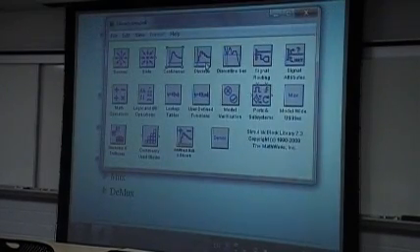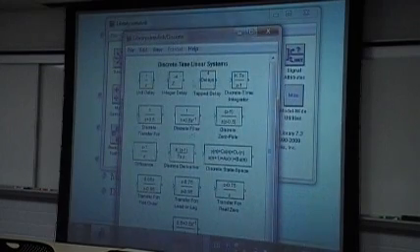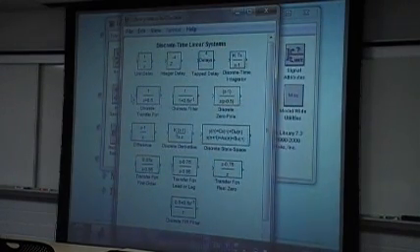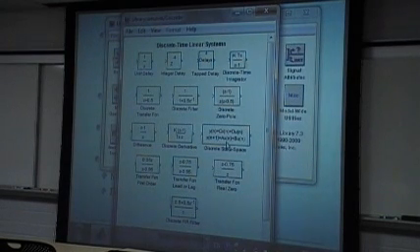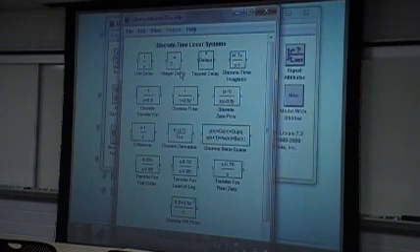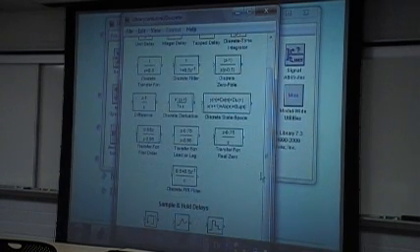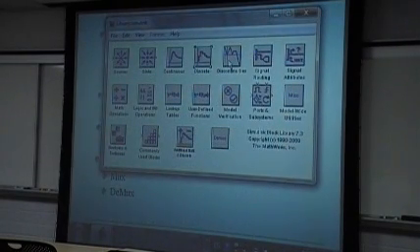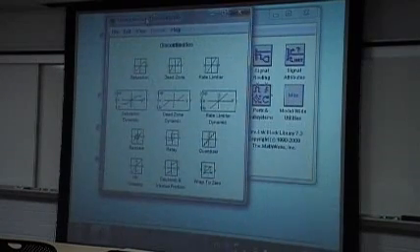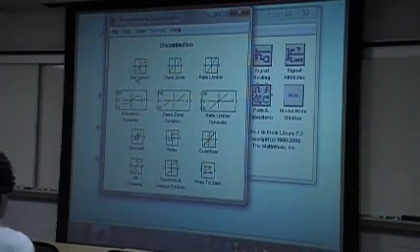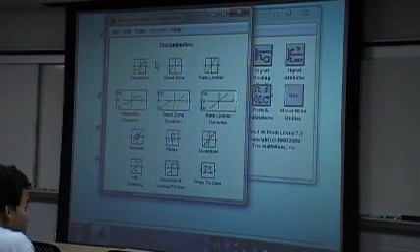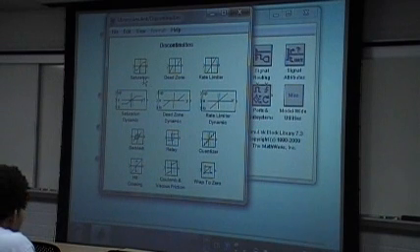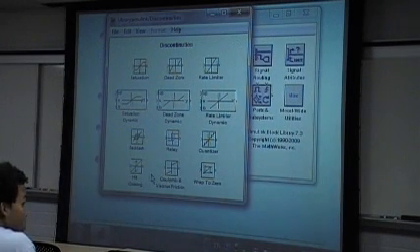And the discrete version of that group includes items like transfer functions, filters, state-space expressions, and delays. So we have similar things. Also, for discrete-time systems, we have zero-order holds and first-order holds. And we can also have non-linear blocks, for instance, saturation, which is useful in modeling control if the system has actuator saturation. We have a dead zone and other non-linearities. Apart from this, we can easily establish our own non-linearities.